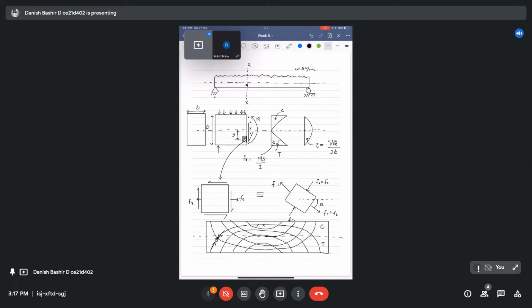Same is the tensile trajectory, another principal stress trajectory coming from the tensile zone. If I see this tensile zone, it will be acting on the fibers like this, trying to elongate them. So if I extend this trajectory like this, I will come to this point. I will see at this element, it will be making it to elongate like this. The same thing I showed on this point. This is compression coming from the compression stress trajectory, and this is tension coming from the tension stress trajectory.